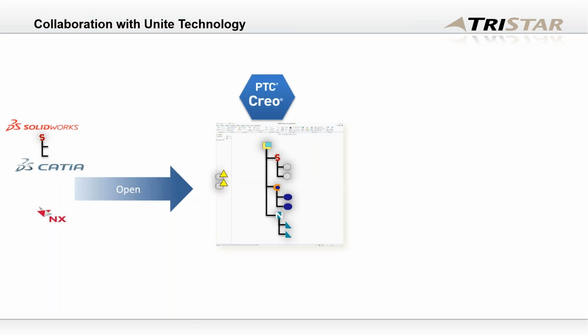You're able to do something called an update, and I'm going to demonstrate this with an example. This is where the collaboration extension comes into play. It is going to review all the non-Creo files in your assembly, and it's going to check what is out of date, whether it's inside of your PDM system or on your local disk. And you're able to update the geometry and any other changes. If you created some new features or some relationships, those are also going to be updated, depending on the change you did, obviously.